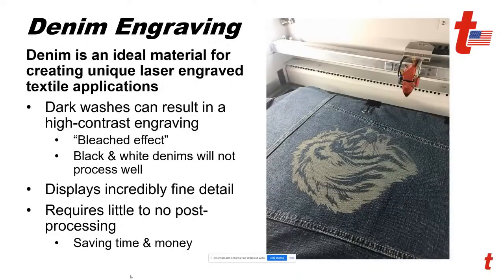So you can just take all the colors in your color palette and change them to a slightly different setting, 2 or 3 percentage points of difference at the same speed, and then engrave them all. Then you dry your denim out, and you see which one produced the best contrast and didn't tear. That's going to give you your ideal setting for production, as long as you stick with the same brand of denim at that point.